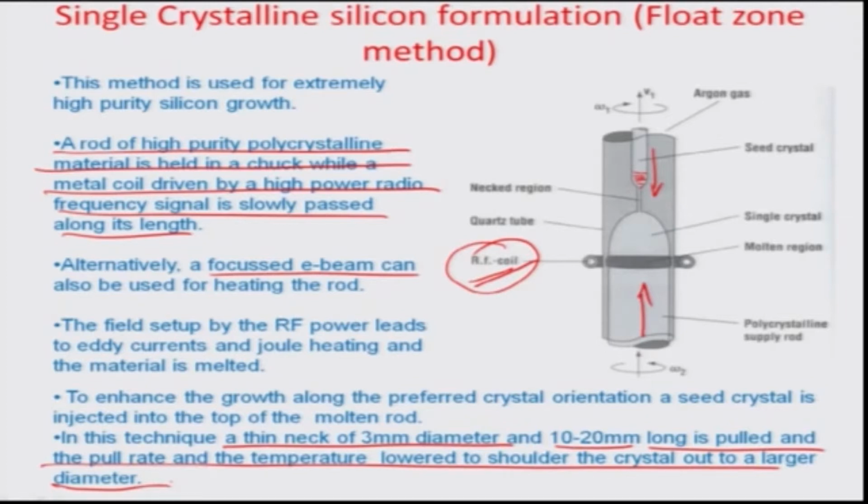So, that is how you can actually get this kind of a larger diameter constitution, even though the oozing out is only through a small orifice or a small cavity. So, you can't really go for a very big size here, because there would be issues related to incomplete supply of the fluid or extremely slow pull rate, which would determine the overall size of the crystal, etc. So, that is another way of growing single crystalline silicon.